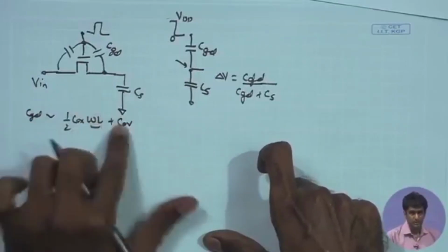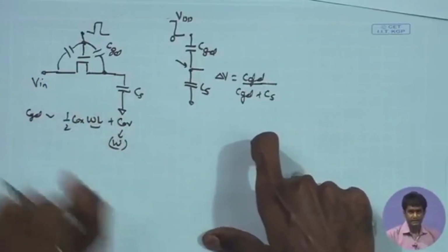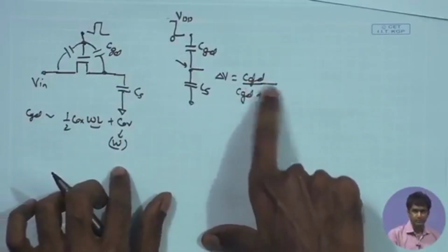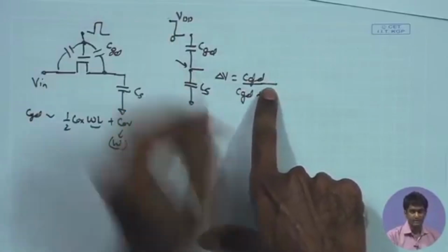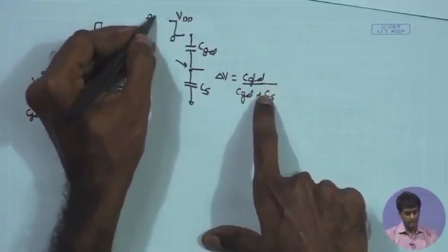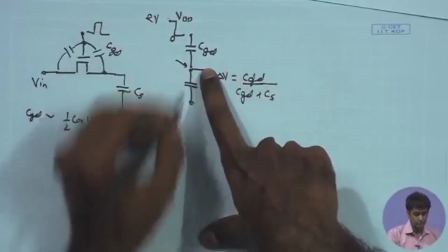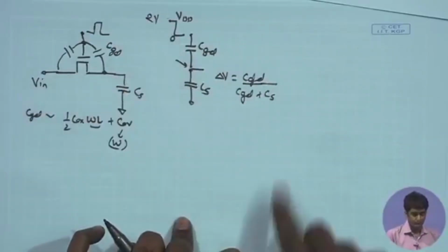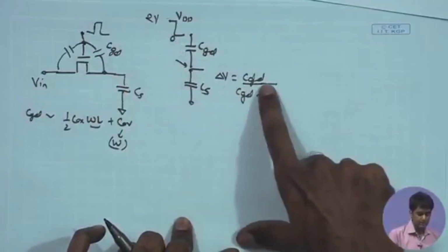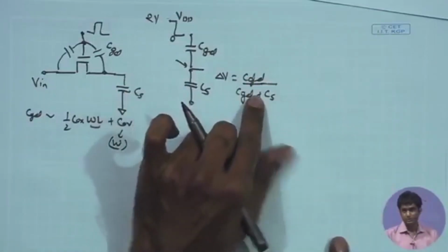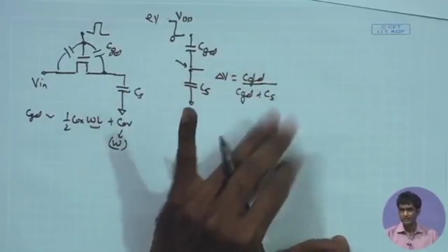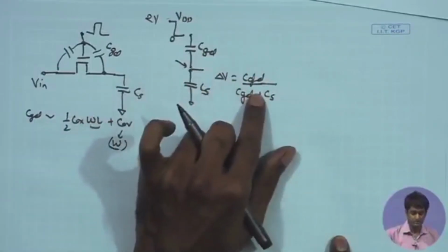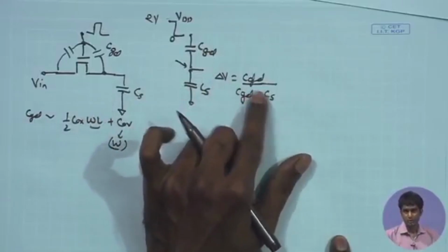So, both dimensions. Basically if you are having a larger size MOSFET, once again to cater to faster speed, you can expect more corruption, and especially here you are having a VDD which is 2 volt, and you would not like this potential to fluctuate more than few millivolts because of this clock action. Therefore, it becomes critical that this CGD is sufficiently smaller than CS, 1000 times smaller than CS. So, once again this is going to impart some lower limit on the value of CS.